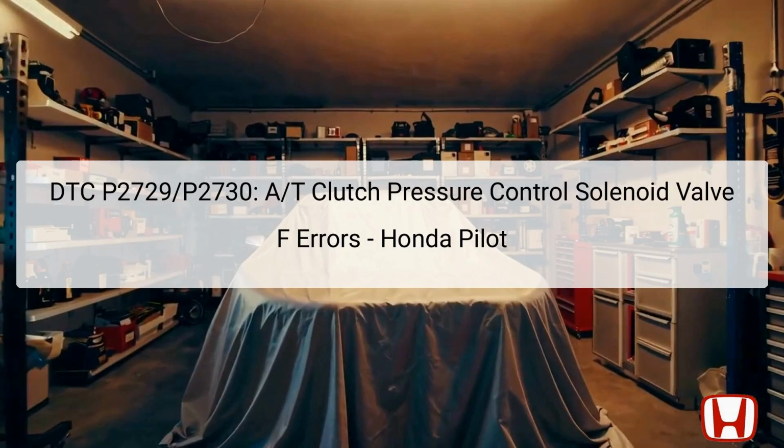These codes are commonly triggered by problems in the electrical circuit and are unrelated to any mechanical failures within the transmission system itself. The AT clutch pressure control solenoid valve plays a crucial role in regulating the pressure needed for proper function during gear shifts. Typically located within the transmission assembly, this component must receive accurate electrical signals to operate effectively. When diagnosing these codes, it's essential to differentiate between electrical and mechanical concerns to ensure that the correct repairs are